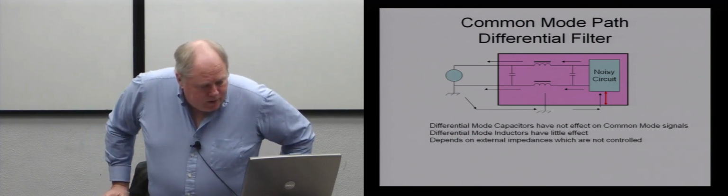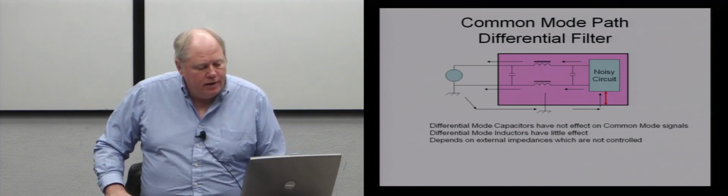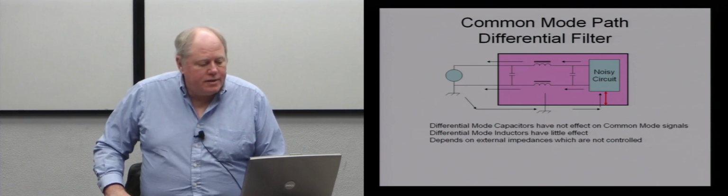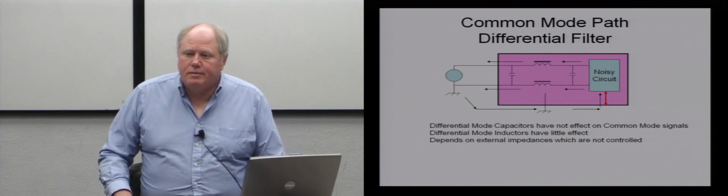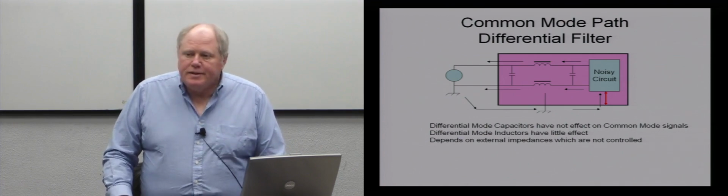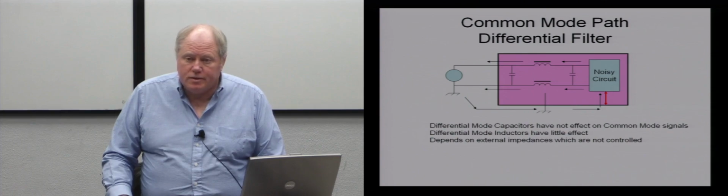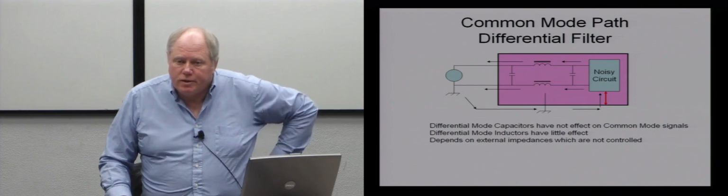ground. The white wire in the wall plug is at the same potential as the green wire. The common and the ground are at the same potential, but they're tied together at the panel, which, when you plug into the wall here, where is that panel? It's in a basement somewhere, I don't know where it is in this building, but it's not really right next door. It's got some distance. It's probably a good low impedance, a fraction of an ohm or something, and that bonding resistance is what's important for blowing a breaker.